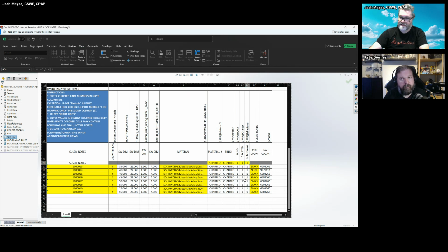And then there's this one called isFastener, which is interesting. That's a SOLIDWORKS property, and it's just a PRP at isFastener, and it just sets yes or no if it's a fastener. There are some tools within SOLIDWORKS where you can exclude fasteners. I think the interference detection is one of those. And so if you have this isFastener property in your model, it will recognize that as a fastener. I think that's inherent in the toolbox library, so I wanted to include that in my custom toolbox library here as well.